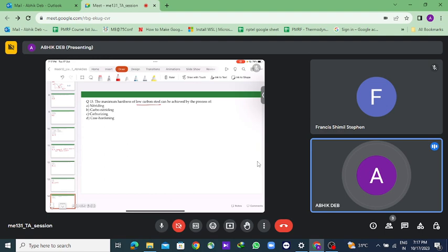So for low carbon steels, the formation of martensite by, say, martempering or austempering, all of these processes will not be beneficial enough. For low carbon steels, we can achieve the hardness by adding compounds. Why add compounds? Because carbon is deficient here. So we have to add external elements. We can add extra carbon or nitrogen or a mixture of carbon and nitrogen.